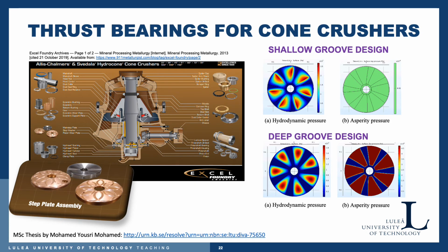The results here on the right show that a shallow groove design generates a pressure distribution looking like this, and a deep groove design will generate a pressure distribution looking like this. Here is the hydrodynamic pressure, the fluid pressure, and here is the asperity pressure.